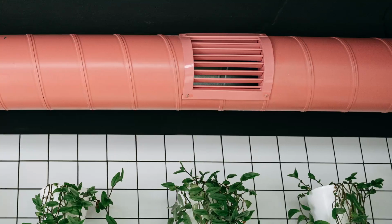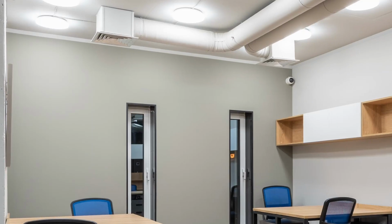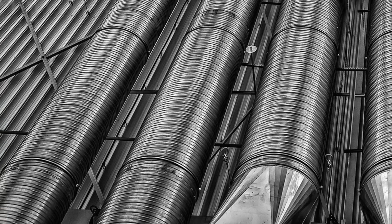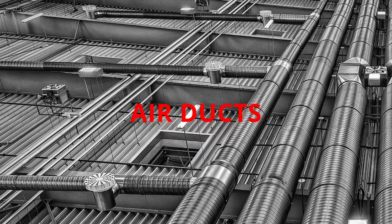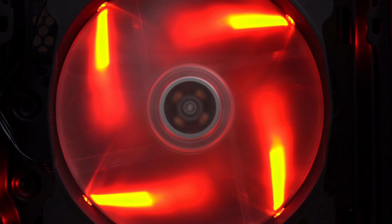Air terminals, such as grills and diffusers, play a significant role in controlling air distribution in the environment. Grills, for example, direct air in a more concentrated way at higher velocities, whereas diffusers evenly disperse air over larger areas at lower speeds. However, it's important to note that the control of air distribution to these terminals is carried out by the air ducts, which connect these terminals to the main ventilation unit of the system. Therefore, proper sizing of air ducts becomes crucial to ensure that the airflow is conducted, meeting specified flows for each area related to the HVAC system, without producing high noise levels.